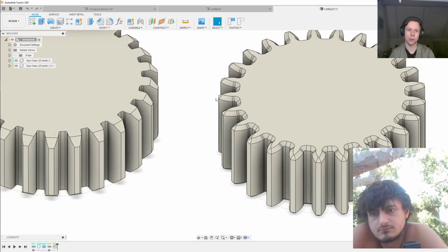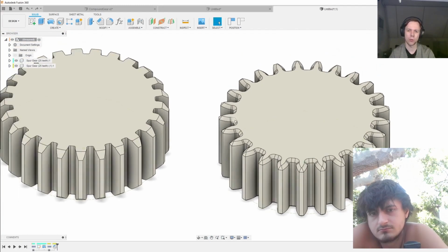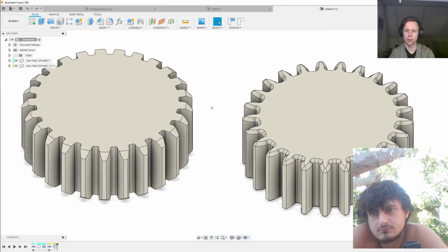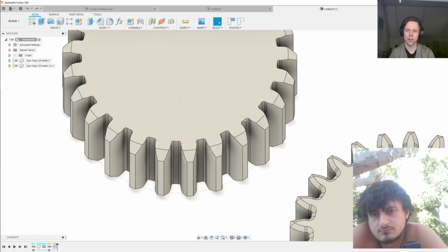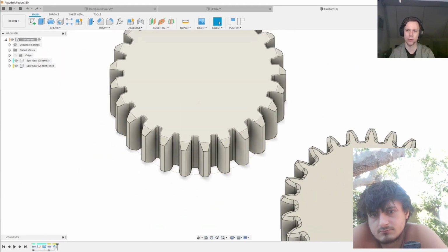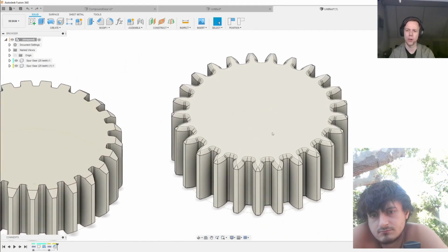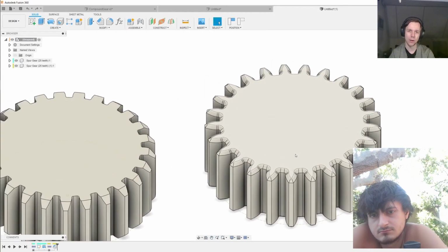The second reason is that if you try to push these gears into mesh, these chamfers will help the two gears find each other so that they will go into mesh. Third, if you use the technique on the right here, the chamfer counteracts the effect of elephant's footing in your 3D printer. So if your printer suffers from a little bit of elephant's footing, then these edges over here being a little bit too wide will cause the mesh of the gears to be quite a bit worse. And you can counteract that by adding the chamfer that you can see on this gear. And finally, as this old Tony teaches us, the chamfer makes the gear look a little nicer, and you can charge more for parts that look nicer.